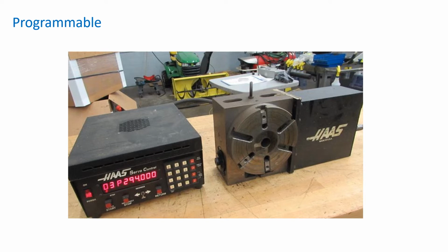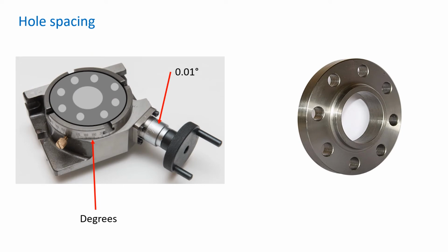Rotary tables come in manual, semi-automatic, and fully programmable for interfacing with computer-controlled machines. Here we can see an example of a rotary table used to machine a PCD of holes, or pitch circle diameter of holes, on a mounting plate.